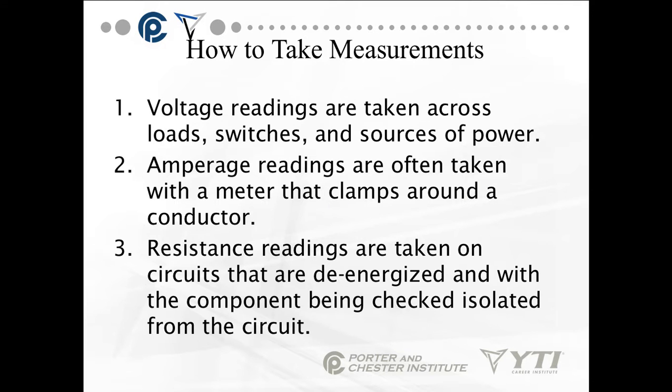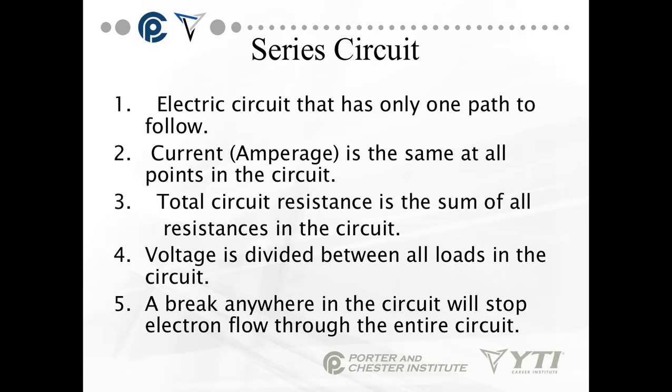We want to take measurements, okay? Voltage readings are taken across loads, switches, and sources of power. Amperage readings are often taken with a meter that clamps around a conductor. Resistance readings are taken on circuits that are de-energized and with the component being checked isolated from the circuit.